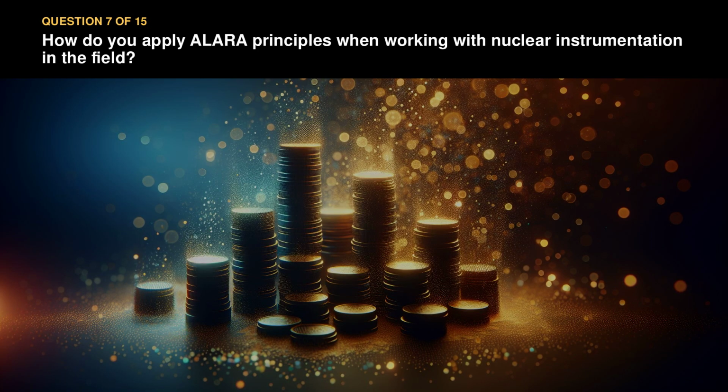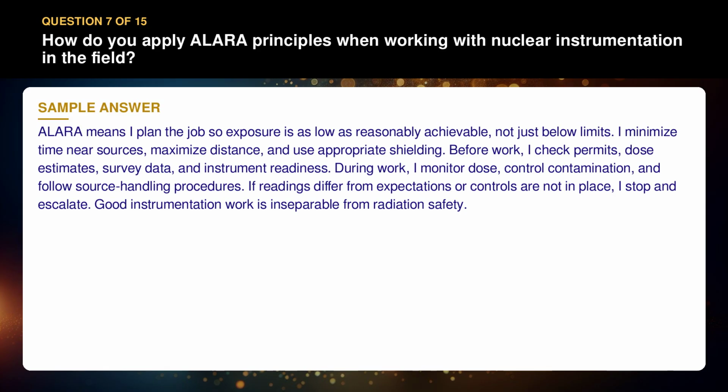Question 7. How do you apply ALARA principles when working with nuclear instrumentation in the field? ALARA means I plan the job so exposure is as low as reasonably achievable, not just below limits. I minimize time near sources, maximize distance, and use appropriate shielding.